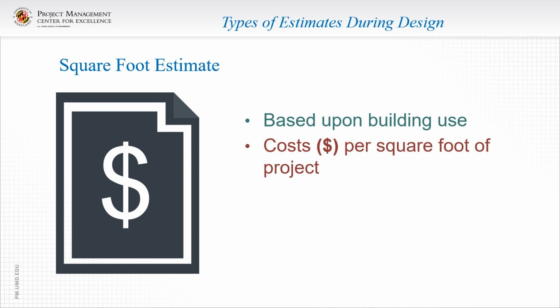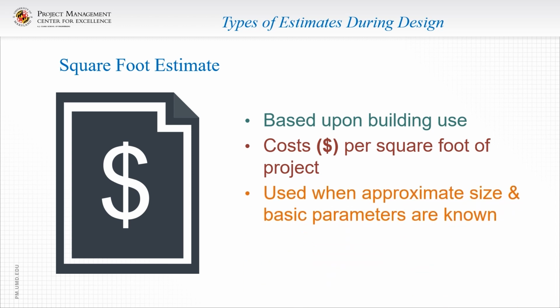The appropriate unit costs are derived from either in-house sources that track past similar projects or outside data sources. This base cost is adjusted to reflect more project-specific factors. Any actual project data that can be folded into this historic data will improve the accuracy of the estimate.